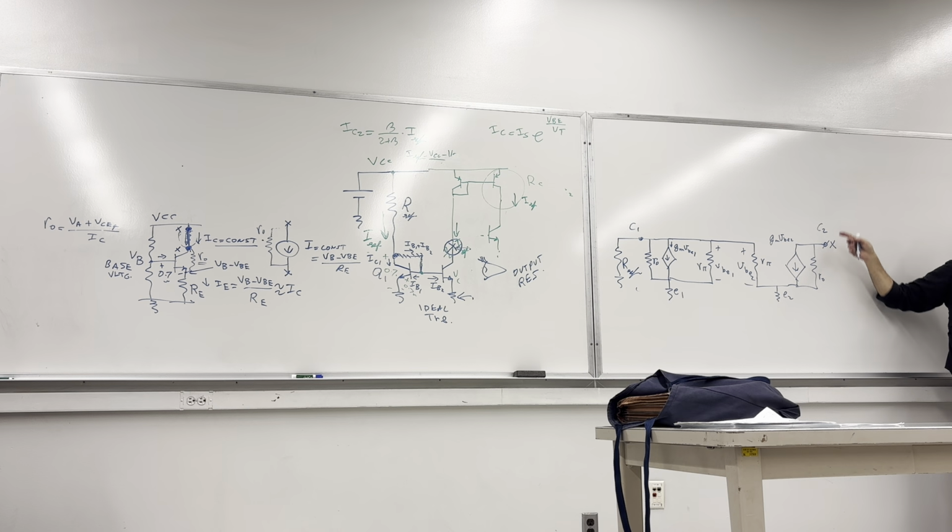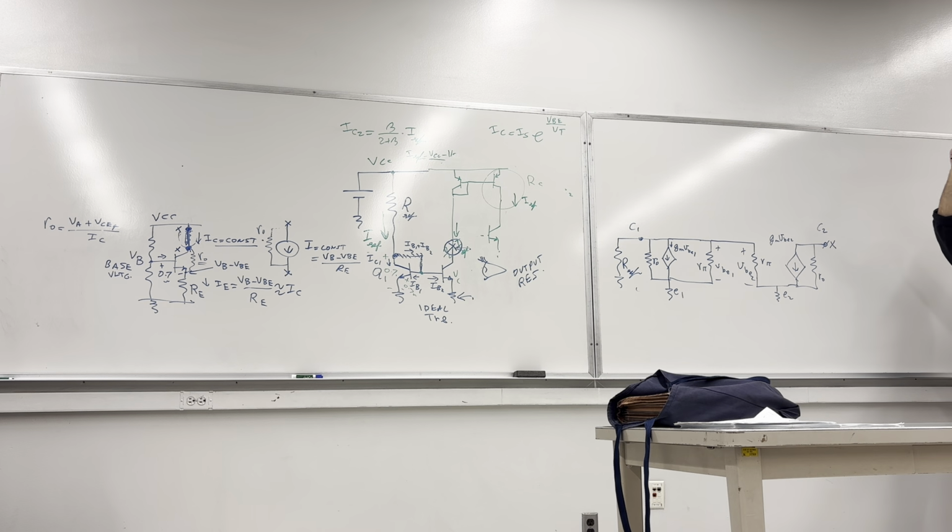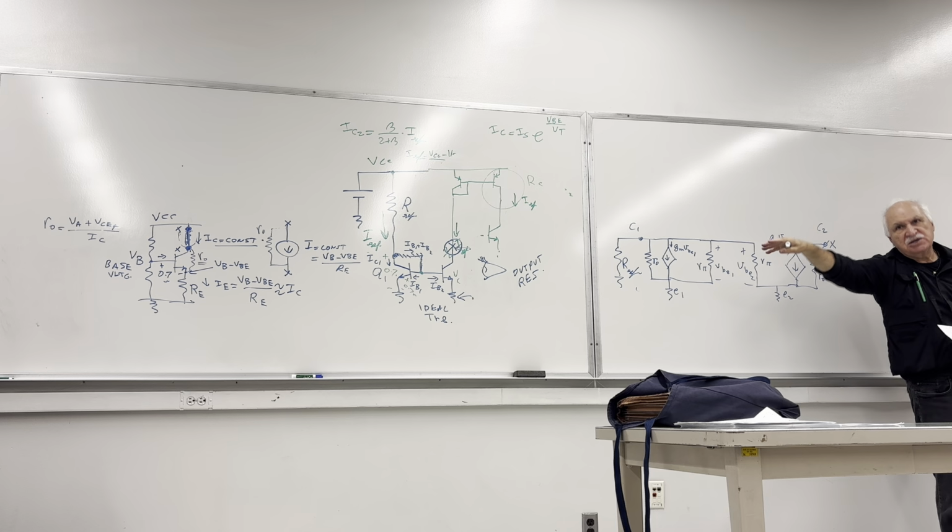Have you ever seen changing IC, hoping to get a voltage at the VBE? Well, we changed the emitter, getting a signal at the collector, like common base. We grounded the collector, fed a signal at the base, and got the output out of the emitter. But we never gave a signal at the collector trying to pick up the output from the base, you see?